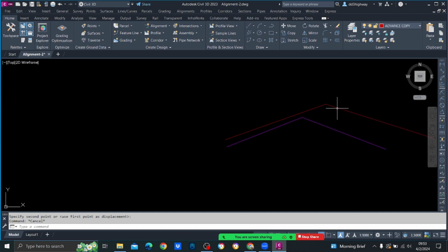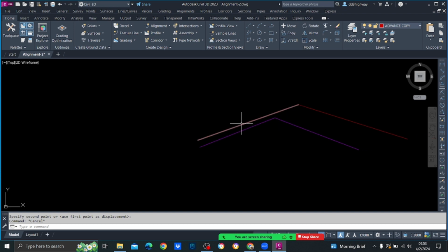Then you check where your new design center line falls, and you had to ensure the minimum thickness everywhere and find out this level. That is how you did it manually. You draw the existing cross section and then draw the new cross section in such a way that 100 millimeter is satisfied everywhere.